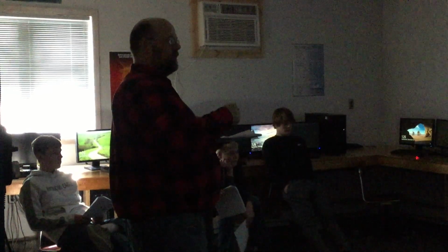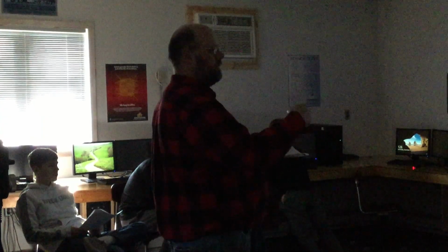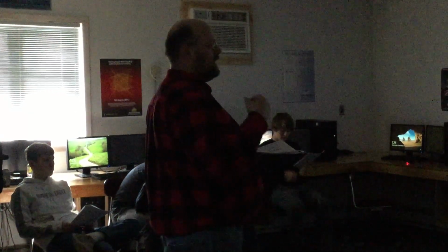So now you can get even more specific about how you have to do your offset of that point. You gotta think that bit's a 1/4 inch, so I'm going 1/8 inch on each side of that point. Or if I'm doing a 3/8 bit, now I'm doing 3/16 on each side of that bit. So there's a lot of things that I can't teach you in one class period, probably even 1 week with this machine. But to do something like this, I think you guys can do.